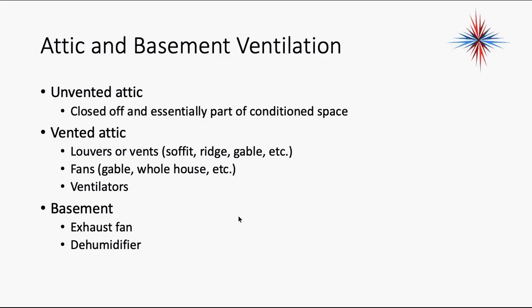The crawl spaces under those trailers, the ductwork runs underneath a lot of times. The main ductwork, if it's not sealed, is going to be sucking in all the contaminants under that trailer. And sometimes that's really nasty.